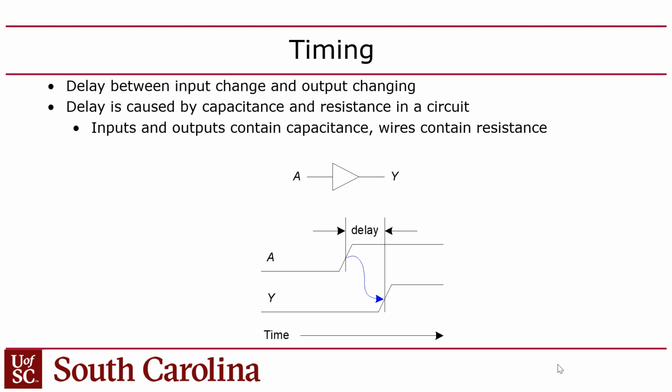But also wires have capacitance. So when you run a wire, that wire is running over a ground plane, right? So you basically have wire, silicon dioxide, which is a dielectric, and then you have another conductor, semiconductor under it. So every wire is a capacitor, and the longer the wire is, the more capacitance it has. That's what the tools are actually doing, by the way.